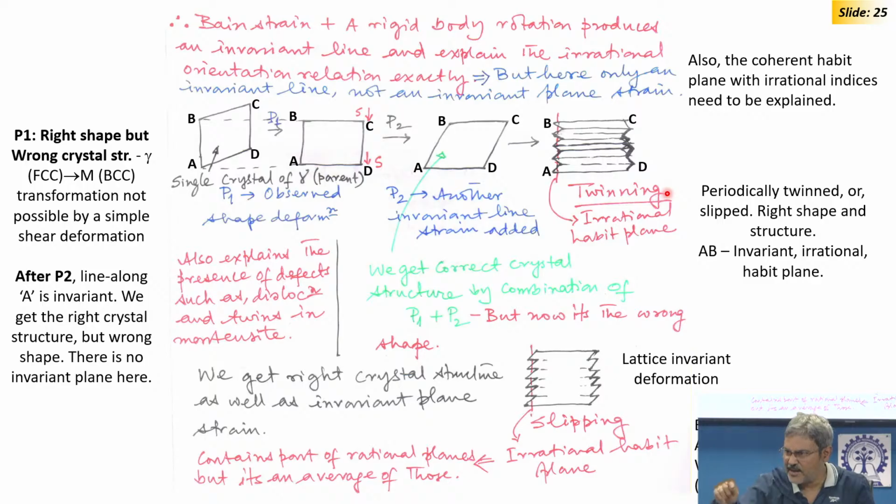If you make a scratch along that plane, you will find that it is just changing, but there is no shift in that line, in that scratch. So, it is fully coherent, it is fully invariant plane. The interface plane is not just an invariant line, but it is an invariant plane. Okay? Although it satisfies an invariant line because a plane contains a large number of invariant lines.